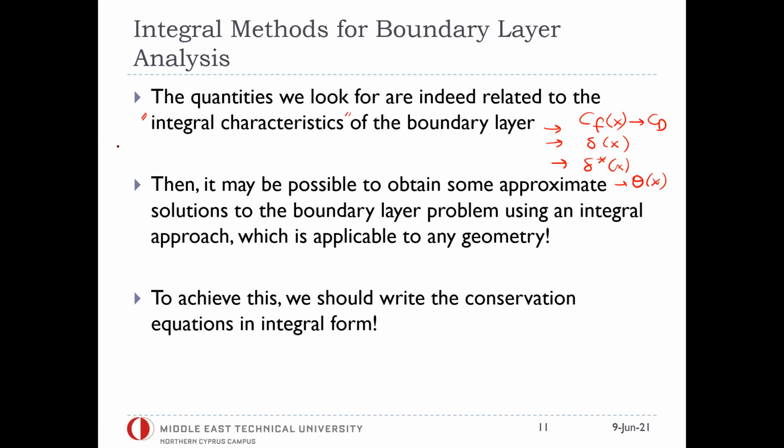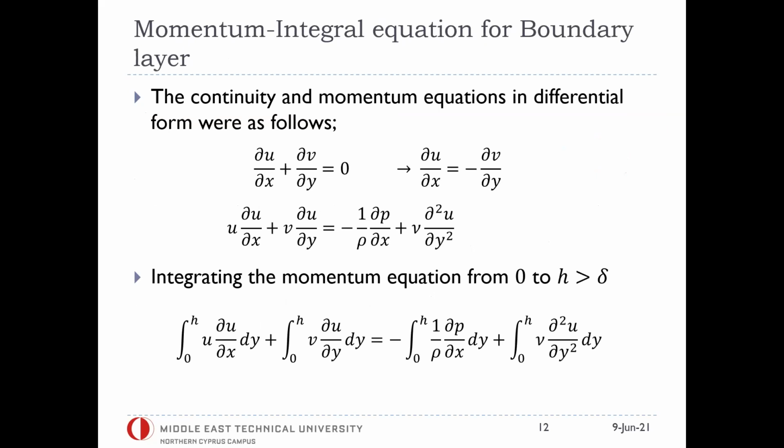So all these are what we call integral quantities. And why do we call them integral quantities? Because if we know the velocity profile within the boundary layer, integration using the definitions of these quantities, integration that includes the velocity profile, gives us these integral quantities. So the idea was, instead of actually applying Blasius's method, meaning change of variables and defining a stream function, can we go through another way, which we call the momentum integral equation method?